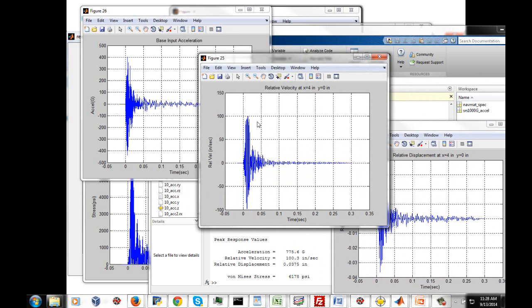Relative velocity is important when we have our Howard Gaberson hat on and we're looking at the stress-velocity relationship, and we just want a quick estimate of the maximum global stress, calculated directly from relative velocity with no consideration of what the natural frequency is. Although to get this relative velocity, we did need to know what the natural frequency was.